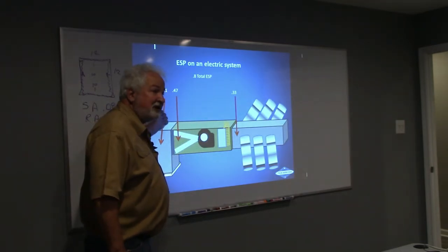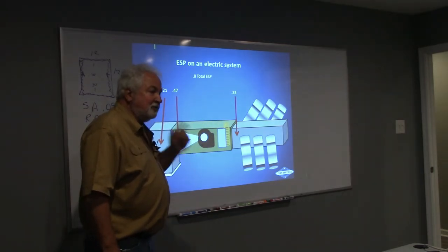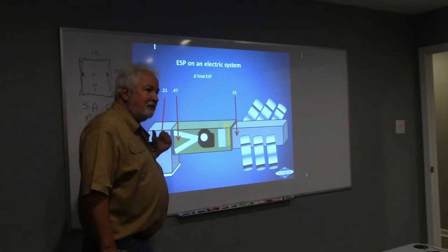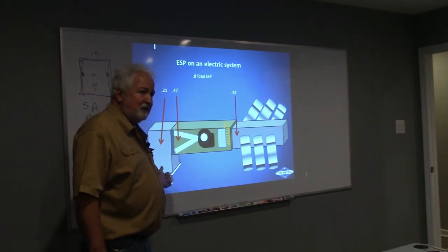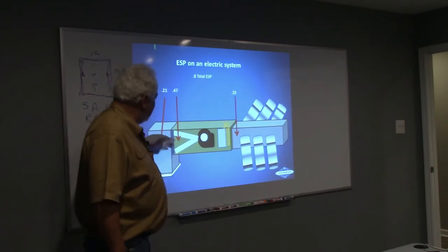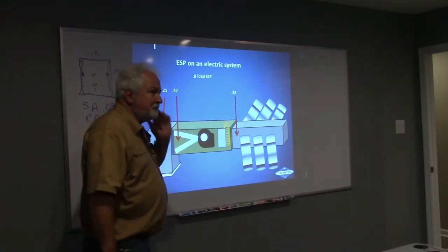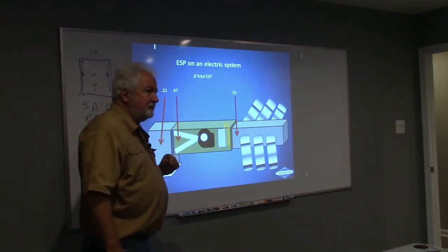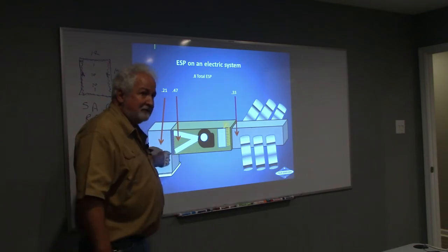What is my return sucking anymore? Is it a sucker anymore? 0.21 versus 0.33? Yeah. Ah, so the problem with the other one was the duct work, not the filter; this one is the filter, not the duct work. Is that making sense? So now if I measure it here or here with no filter inside there, it's the same. You got it. Are you seeing how that tool can save your butt?